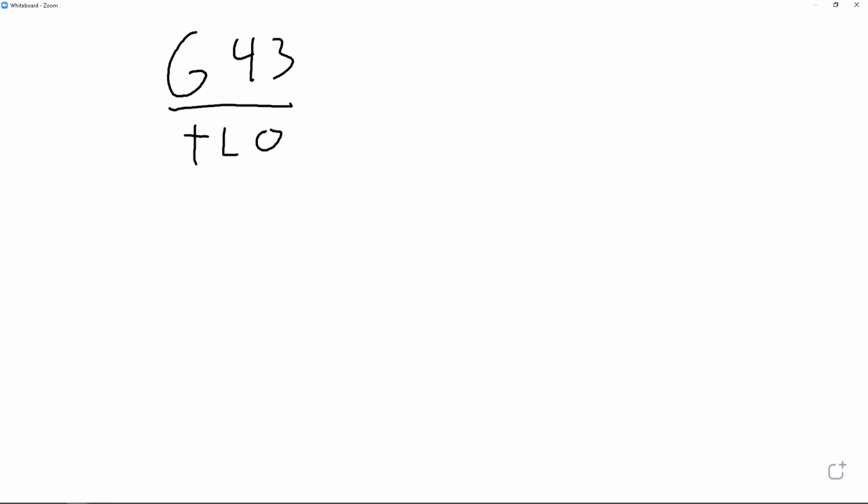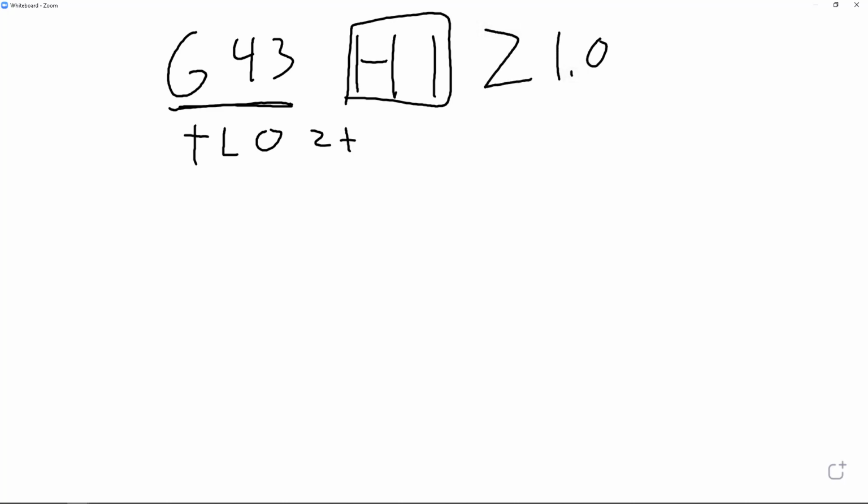Okay? So it says comp Z positive, okay, to a value, H1. This value is in the controller, and I'll talk about what we're going to do to change that up, or how to derive that value. And it's almost always wise to give it with a movement, Z 1.0 or 2.0 something. So compensate Z positive using this value going to this location in Z. Remember, before this, you're going to have G54 or whatever work offset on already. So the Z value, depending on how you touch your tools off, is going to be in there.